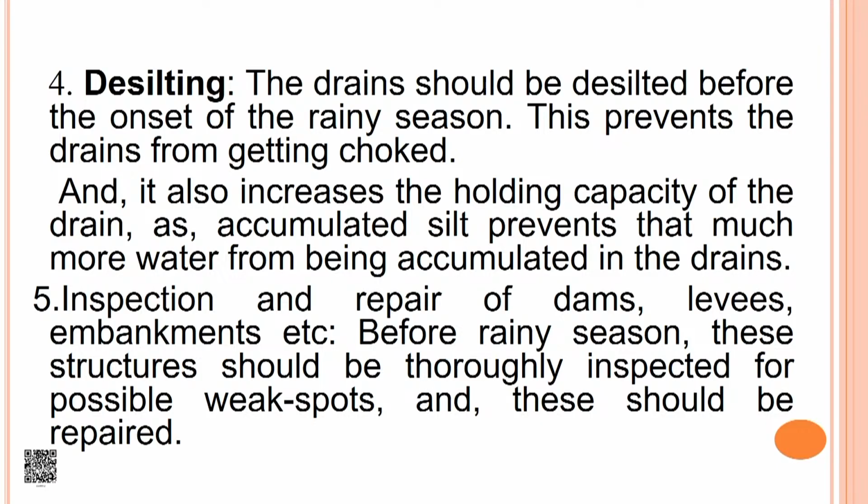Inspection and repairs of dams, levees, and embankments before the rainy season. These structures should be thoroughly inspected for possible weak spots, and these should be repaired beforehand.